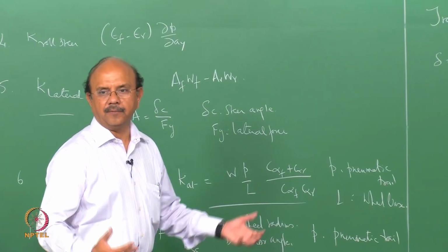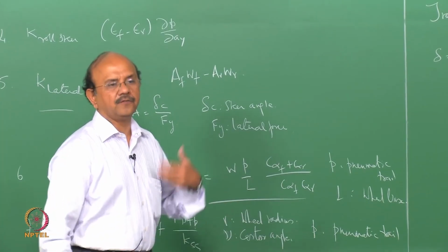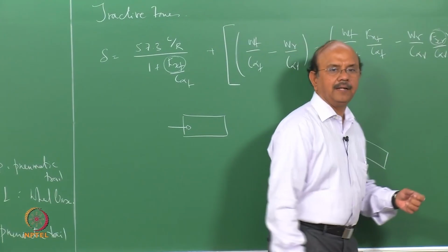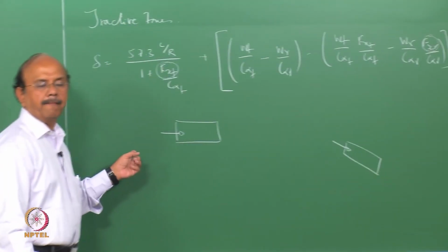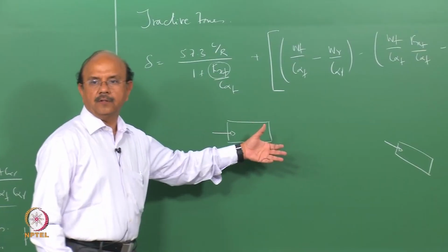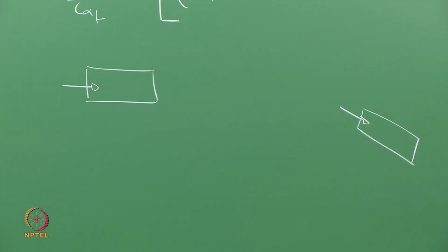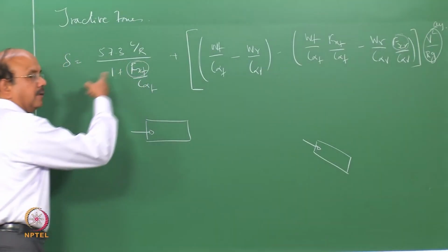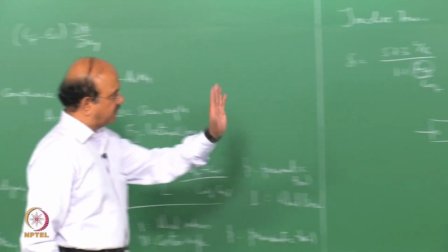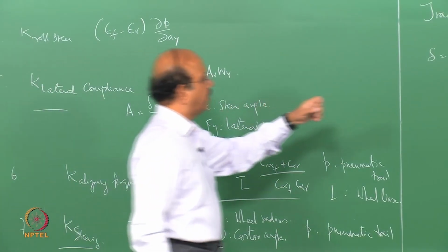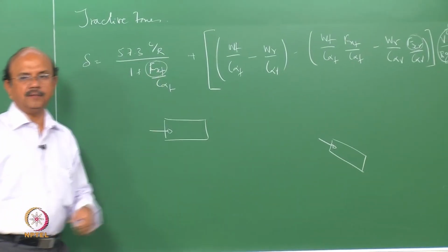So for example, if it's a traction and if it's a front wheel drive, then FXF is what you will get, and if it's just a front wheel drive, you won't get FXR whenever you are accelerating, right? Now look at this, what happens. So even for a neutral steer where the rest of it are not there, in other words, the first geometric term is affected by the traction.